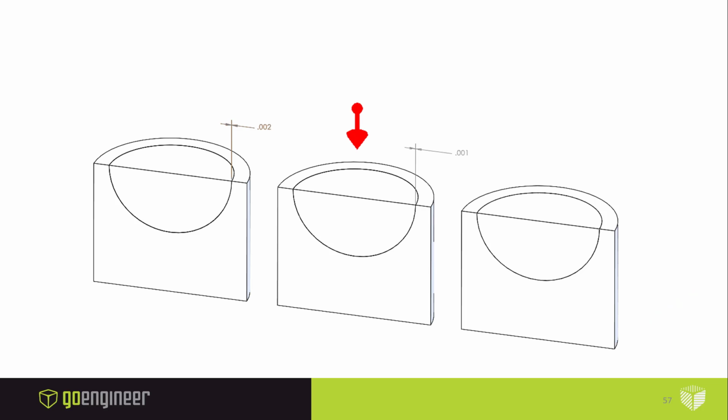To test these correction factors, I've created a spherical ball and fitted it into a spherical hole, and also used different gap sizes. Here we have 0.02 of an inch gap between the diameter of the ball and the diameter of the cup that it fits in. Here, a 1,000th of an inch, and here they're contacting each other perfectly.